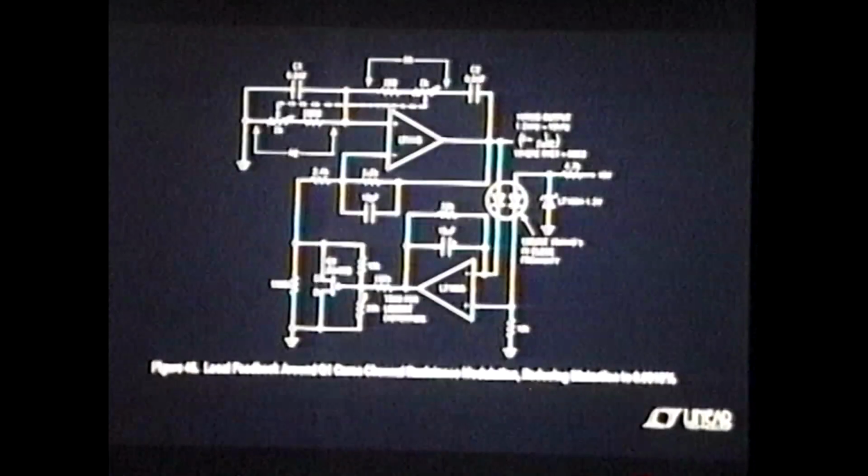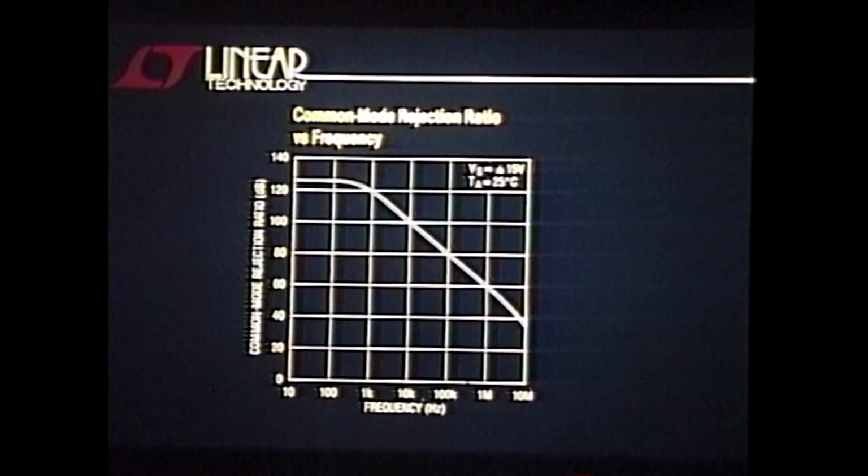Now if I go look at the data sheet of the amplifier, look at that. Look what happens to common mode rejection versus frequency. It goes away. I've got a circuit that's very demanding of common mode and frequency. There's lots of signal swing at those inputs, and I'm asking the amplifier to balance it. That's likely to be the villain.